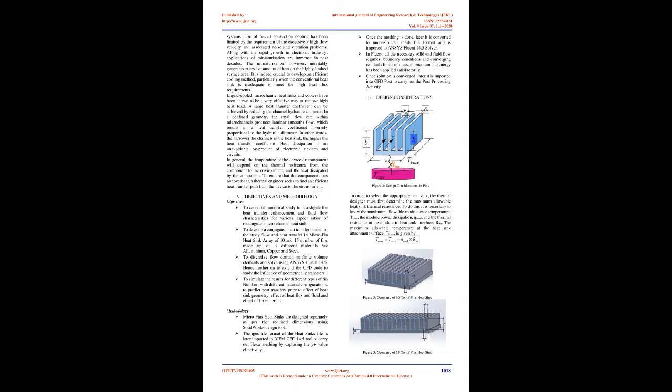Sheikholeslami et al. [14] had carried out an intensive research on the influence of magnetic field on the copper oxide water nanofluid flow and heat transfer characteristics using the lattice-Boltzmann method. The Koo-Kleinstreuer-Li correlation was employed to calculate the thermal conductivity and viscosity of the working fluid. They concluded that the heat transfer characteristics increase with increase in Hartmann number and heat source length and decrease with Rayleigh number.